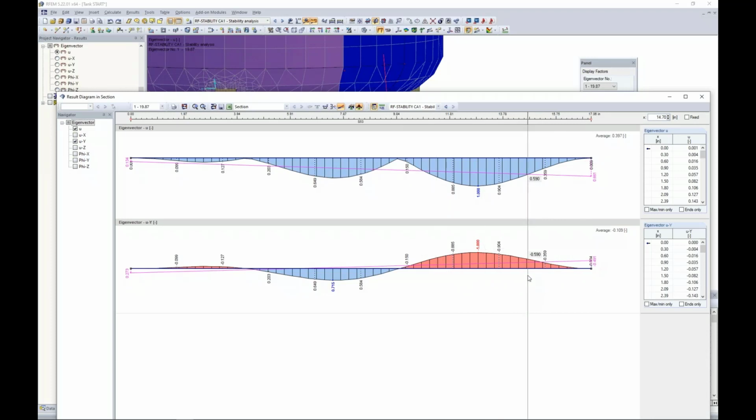So what we want to do here then is to model the imperfection, keeping this into consideration with these tolerances. And I also want to backtrack and just mention something like the AISC 360 tells us that we should really model these imperfections directly. There are other alternative methods such as applying notional loads and such, but in some way or another they should be accounted for. So we're going to refer to the AISC Code of Standard Practice.